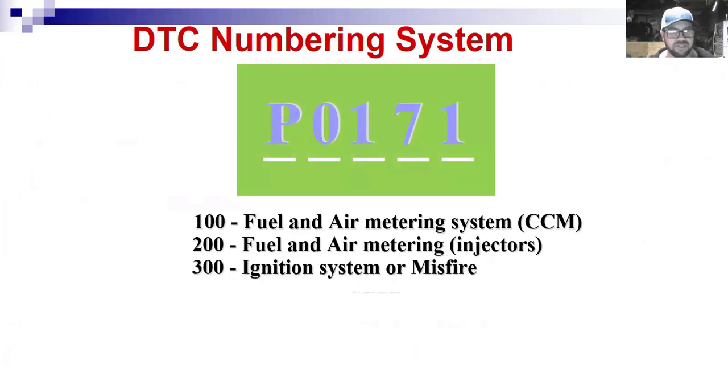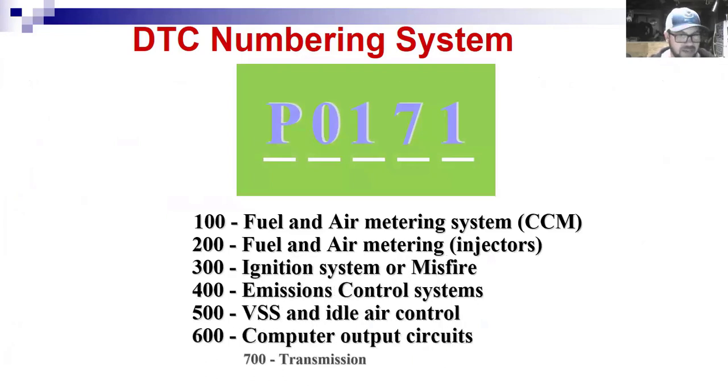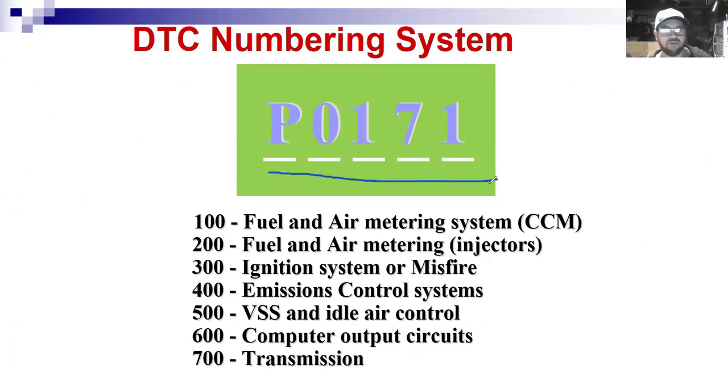All right. So with all that, let's go back to this. We're looking at the codes. And remember with OBD2, when it came out 20 plus years ago, this was a huge leap forward, because before we had all kinds of different codes. Now we have a standard alphanumeric coding system, which means that for instance, a P0171 means the same thing on a Toyota as it does on a Ford or a Chevy or even a Volkswagen. If this second digit is a 0, it's a generic code, and that means it will be the same on any make and model that is OBD2 compliant, which is awesome.